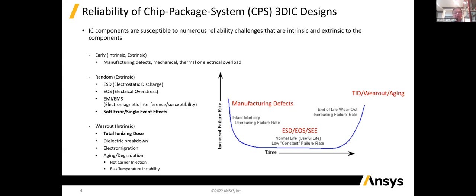And there's a new failure mechanism related to silent data corruption, as mentioned by Jimmy. It may be caused by soft error, maybe caused by single event burnout or single event effect. And that may be related to the radiation coming from alpha particles for the total ionizing dose. So these are new problems that, even if you have a data center, you cannot prevent, and they can cause serious silent data corruption.